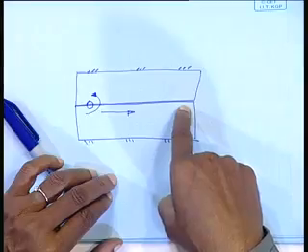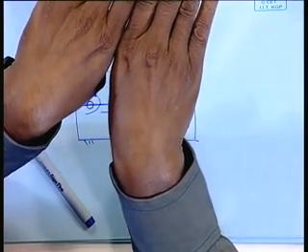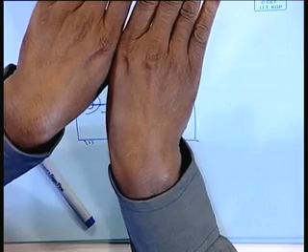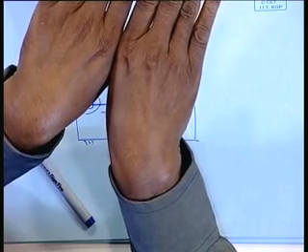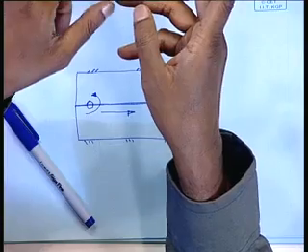So, obviously, you will have to have the plates clamped strongly such that they do not move apart, because the root gap has to be 0. Root gap 0 means two plates should remain in touch continuously, because if there is some root gap, there is no question of filler metal here, so welding will not be proper.